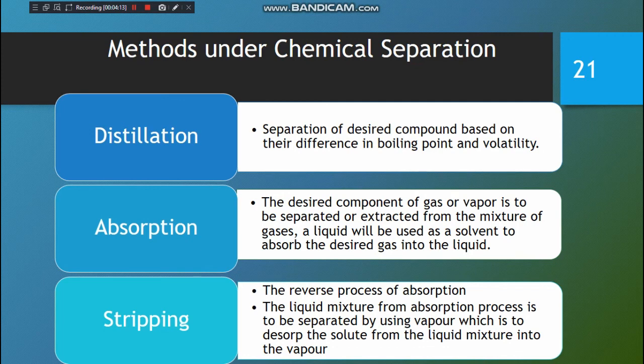Meaning that distillation is a process of heating the liquid to its boiling point, condensing the vapor back to a liquid by cooling, and then collecting the liquid as the distillate product. Since different substances have different boiling points, controlling the temperature allows separation to occur. As an example, as I explained in the previous slide, for the fractionating column, crude oil is refined to various products such as naphtha, gasoline, kerosene, fuel oil, and lubricating oil through a fractional distillation process.